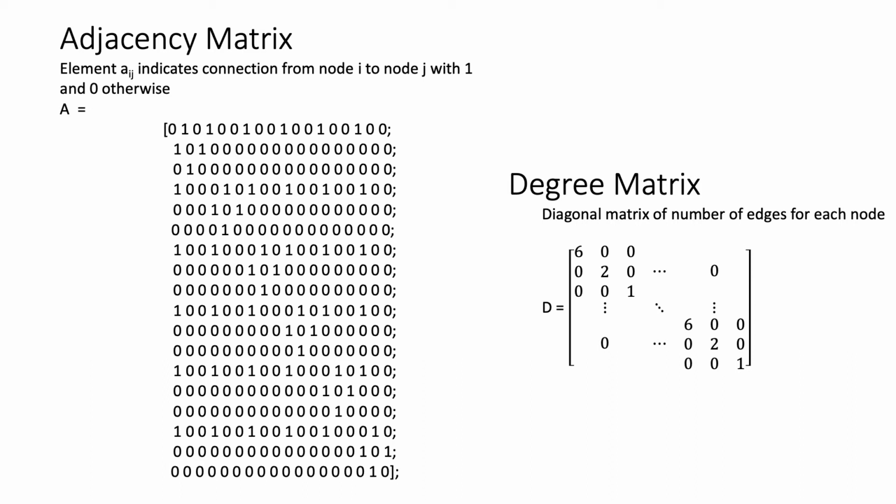And the degree matrix is a diagonal matrix, which is also 18 by 18 in this case. And the diagonal elements will be the dependency of each node, which means the number of edges that are connected to each node. And we can see that the structure of the degree matrix for the hexapod graph model is a repeating block diagonal matrix due to it being a star-shaped graph, meaning the central nodes have higher dependencies and the nodes that are further away from the body have lower dependency.